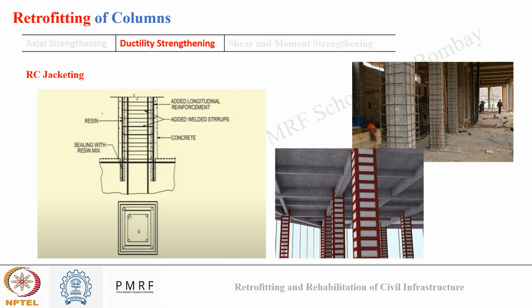How? Simple: by adding longitudinal reinforcement attached to the old concrete by epoxy, adding stirrups to enclose the new cage, connecting these new stirrups with the old concrete column, and then at last concreting the cage from the top, either using conventional concreting after placing formwork, or by using shotcreting if possible.